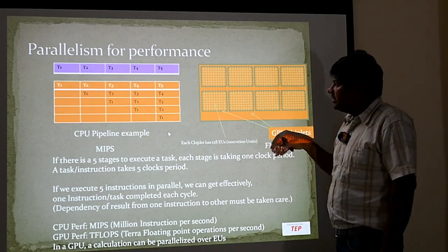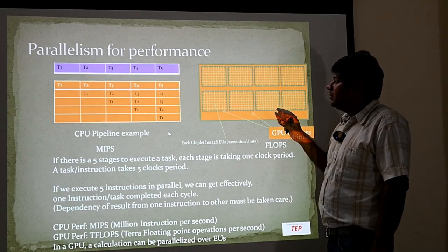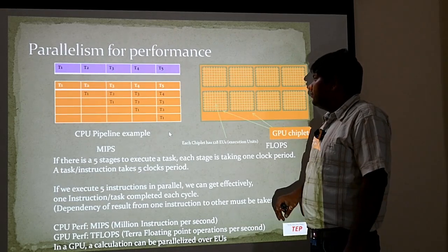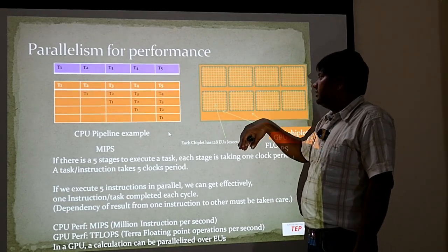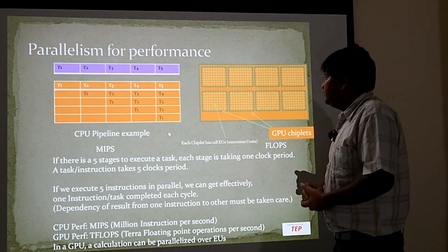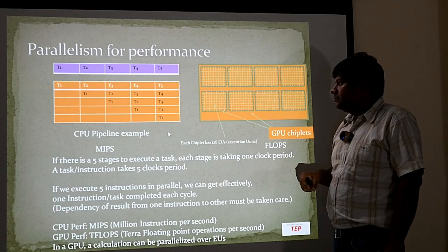There are many other advantages that do come with this that we will discuss, but primarily in the sense of power, rather than running one array of execution units at very high frequency, it is advantageous if we are using 8 sets of the same block at the lesser frequency.